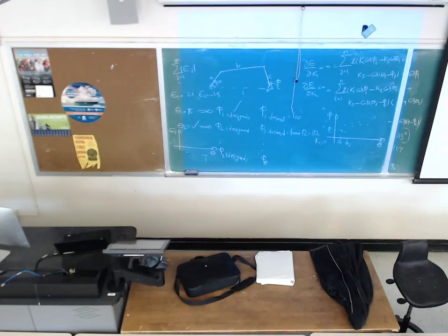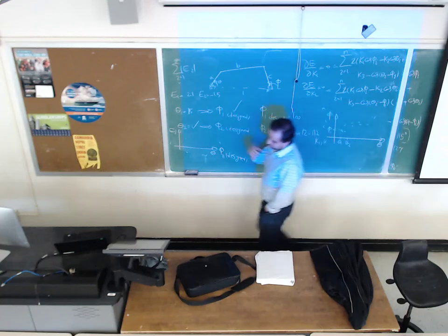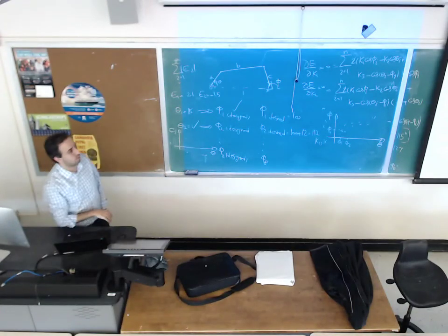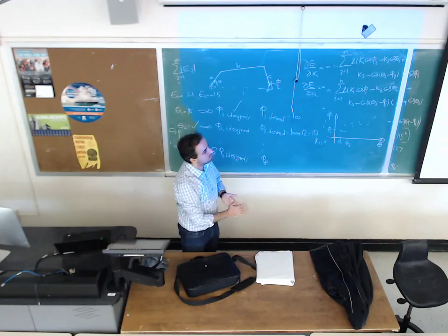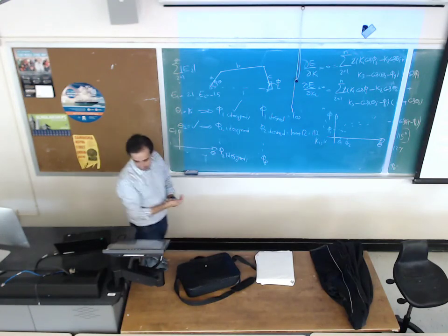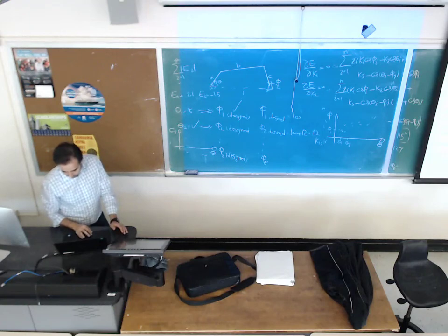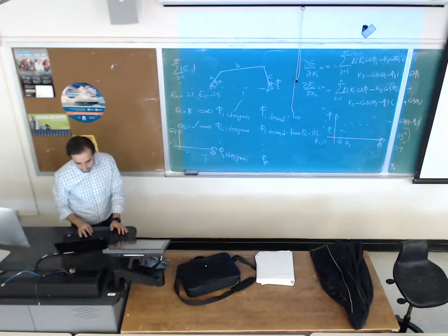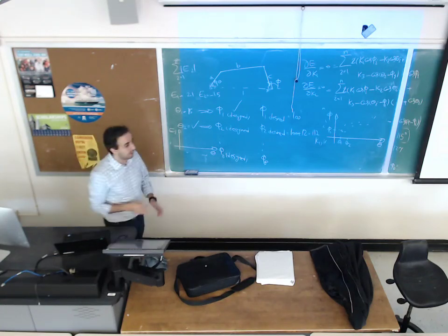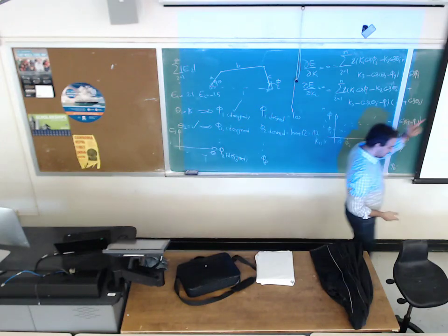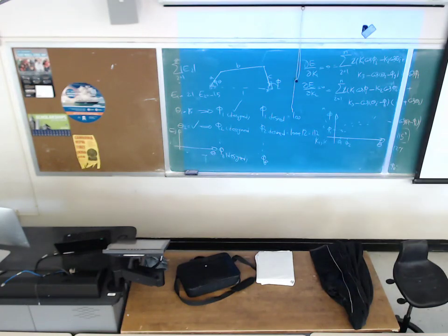But we would like to have a crank rocker. So the free choices that you pick should give a result such that the mechanism is a crank rocker. If it's not, you have to try another set of theta 1 and phi 1. Okay. Problems 3 and 4, you should wait until the Monday class and follow this.